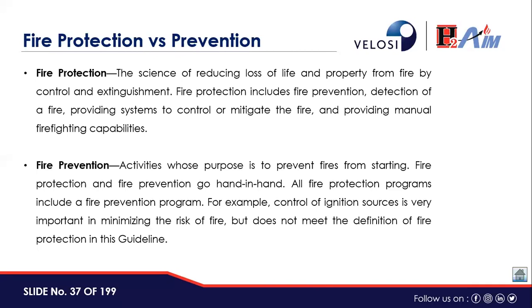Under the firefighting system, there are two types: active fire protection and passive fire protection. Passive fire protection means if there's a fire, the building or structure should not collapse quickly, so fireproofing is done for a 1 hour or 2 hour fire rating, depending upon applicable laws and practices. Underwriters Laboratories provide certain guidelines for that purpose. Then we have active firefighting systems, whether water systems, foam systems, or chemical systems, where you apply those various firefighting systems.